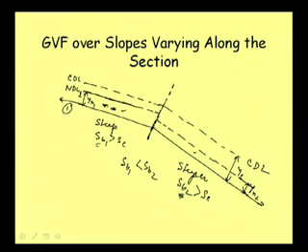This is not getting disturbed because it is supercritical flow, as I explained earlier, it will be coming like this. And so far as this downstream section is concerned, this depth of flow will move, after a certain distance, to the normal depth line. So, the change will occur from this point to that point, and that will be coming like this. It will be moving like this.